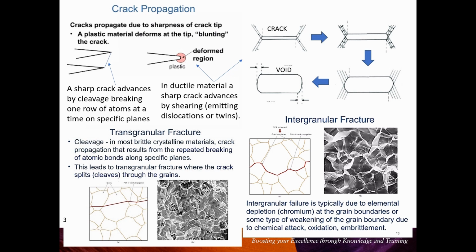Basically a substantial fraction of the elastic modulus, and we're talking tens of gigapascals in terms of a localized stress, to basically decohere a material. But especially for nuclear reactors, one does not use brittle materials such as this in nuclear reactors. They're very rarely used. And the only time that one would come across cleavage fracture would perhaps be in a body-centered cubic material and at very low temperatures.